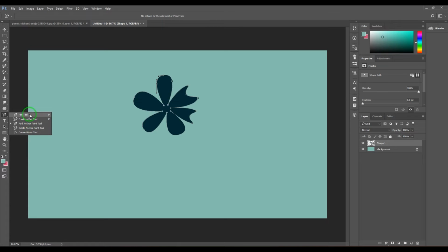So I don't think these three tools are necessary to pick there. Directly, you can be in the pen tool and access Add Anchor Point, Delete Anchor Point and Convert Point tools. How? Hold Alt for the Convert Point tool. Put your cursor on the curve, it adds anchor points; put the cursor on the anchor points, it will delete the anchor points. So simple. So you got how you can generally put points and what types of points you have.